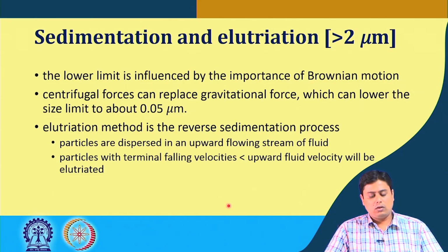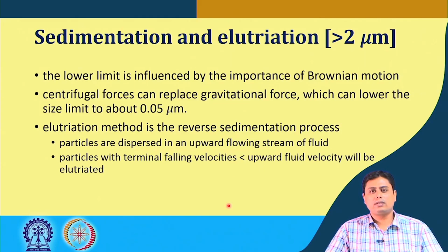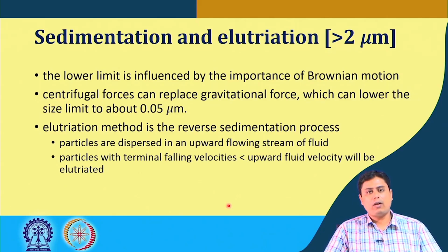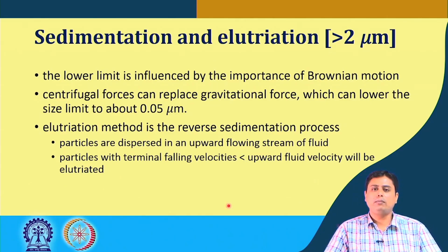Centrifugal force can replace this gravitational force. Instead of the simple normal settling case, we can introduce centrifugal forces in that domain to enhance the settling process, and in that case a size limit of about 0.05 micron particles can be settled, because you can understand that such lower size particles under normal settling conditions may not settle and can be suspended forever.